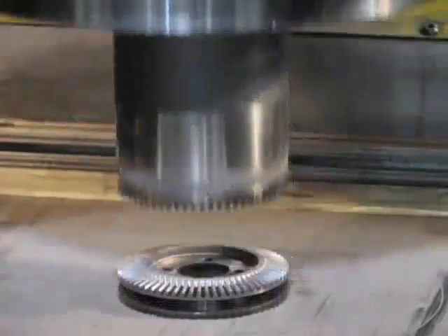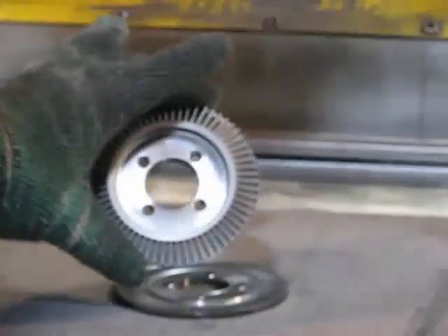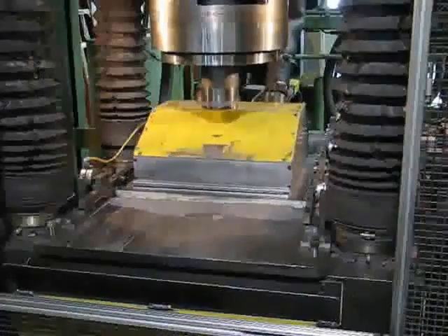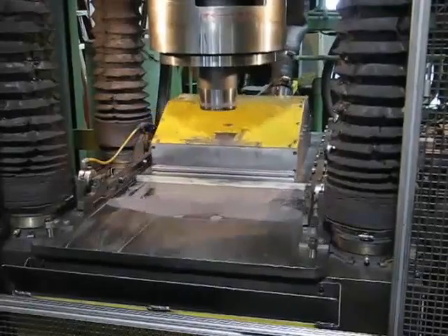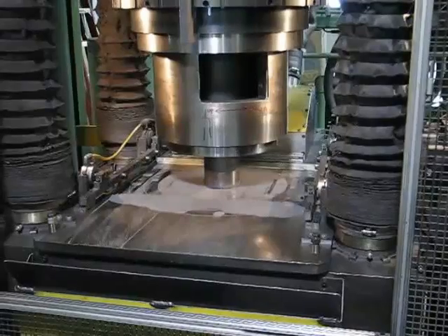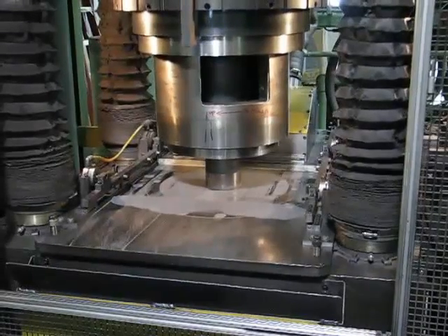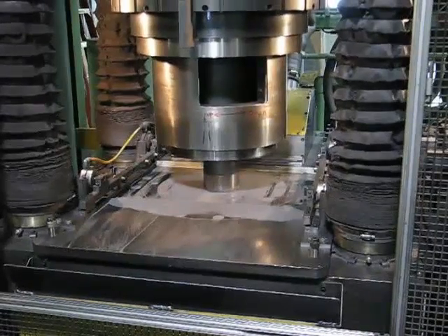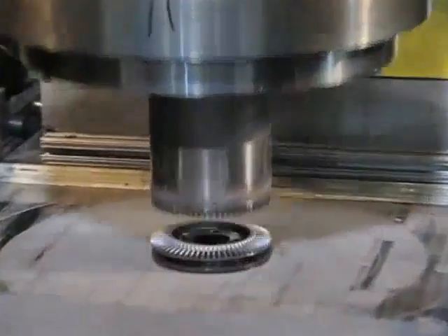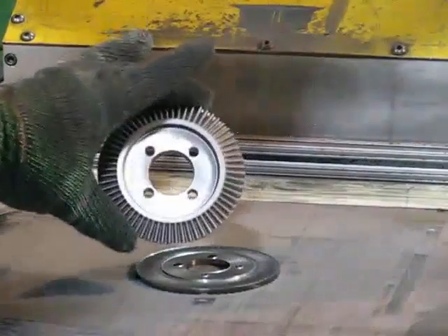The other qualification I'd like to say for length: there is some limit to powdered metal. We would be remiss if we said that we can make everything. Up to about a 3-inch long part is possible. Much over 3 inches, and we begin to lose the mechanical properties that you might need. So again, up to about a 3-inch long part is very doable in powdered metal.